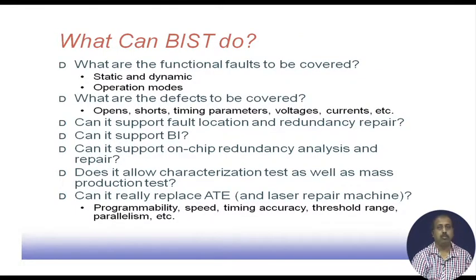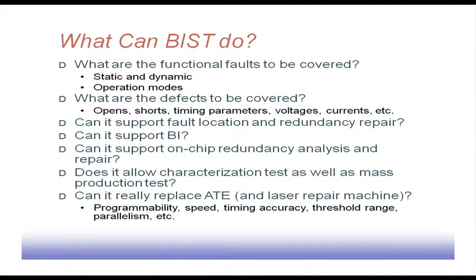Next, we will look into memory BIST. Basically what we have said is that there is a March test sequence that we need to apply to the memory for testing it. But how do you apply those test patterns? Are we applying from outside? If we are applying from outside, then we have to have all those controls. Okay. So, we have to access individual cells, and then we have to send individual patterns and all that.